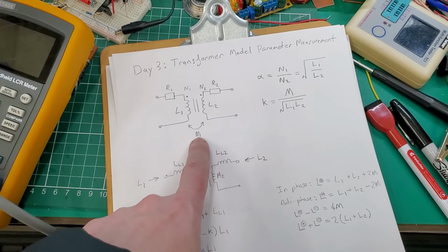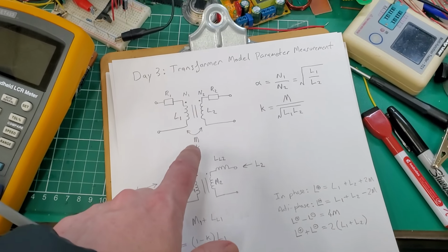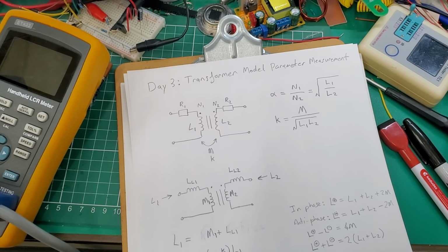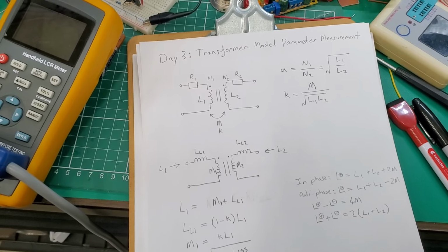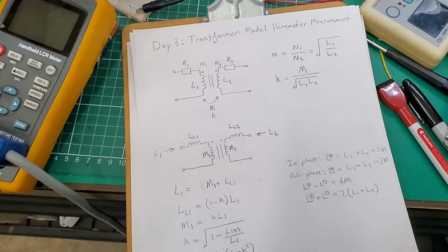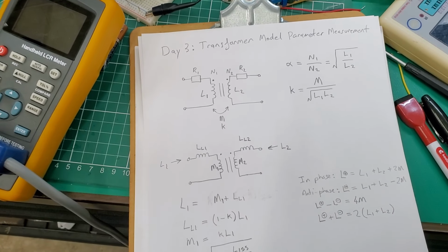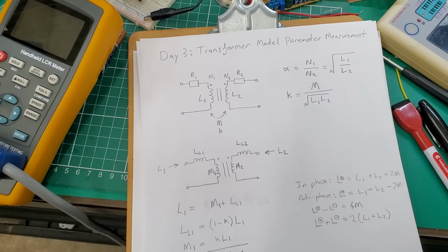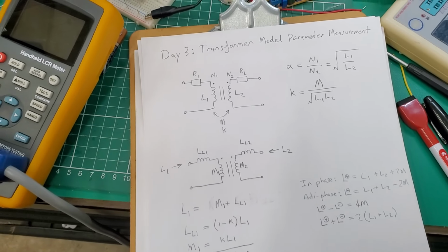In general, these two mutual inductances are different, but the coupling between two conductors is defined by this one mutual inductance. It's interesting, actually. Physics-wise, the mutual inductance between two arbitrary conductors is computed the same way as a self-inductance. So you could say self-inductance is just auto-mutual inductance, which I guess is why it's called self-inductance, right? If you put in the geometry of the filament, or however you model the actual current distribution of a conductor with itself, that'll give you its self-inductance, and if you model it with another conductor, that'll give you the mutual inductance between them. But I digress.